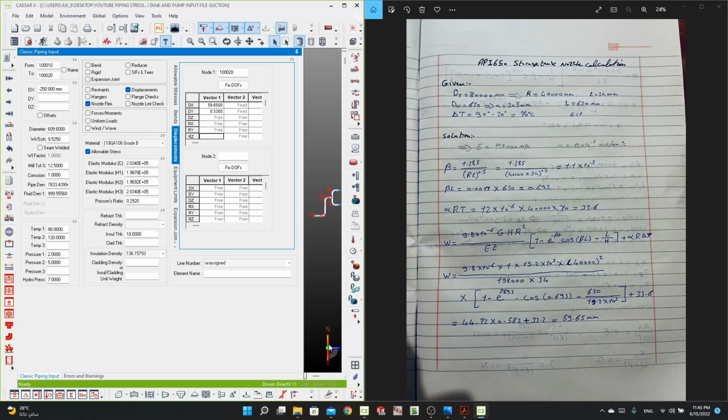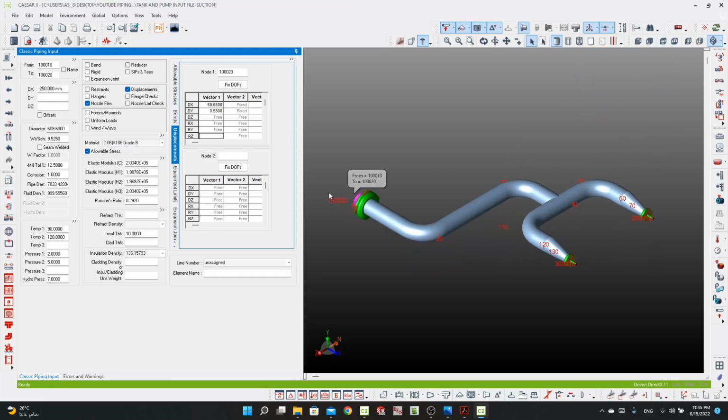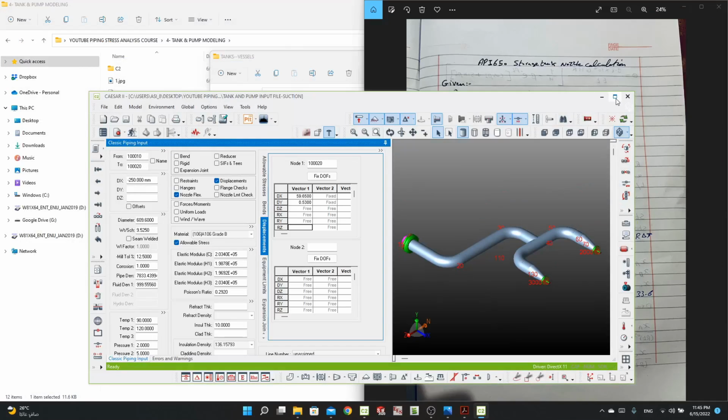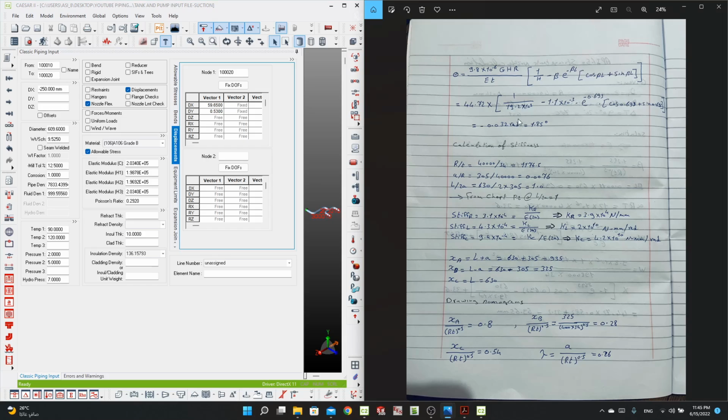And we will insert the rotation. The rotation will be in the tank, since our calculation here is like that, so the nozzle will be bulging, the theta will be rotating in the z direction, so we need to put the rotation in the z direction. So theta, take care, this theta is in radians, we are using degrees, so we need to put this one, which is 1.85.